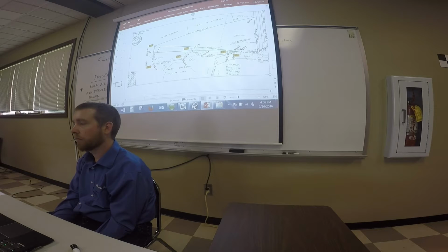Create those coordinates, I inverse back out to the road, and I'm off two-tenths on the one out of the road. What's Craig going to say? Drive that pin if you don't find it. And now we just saved entire site mobilization, moving equipment out there, getting set up, just to set one pin.